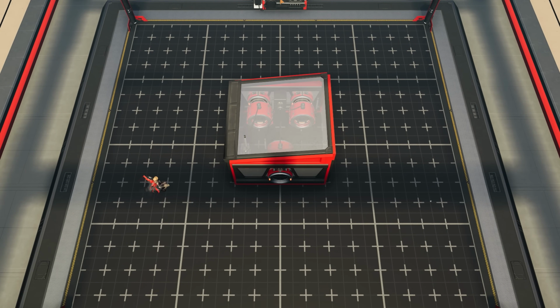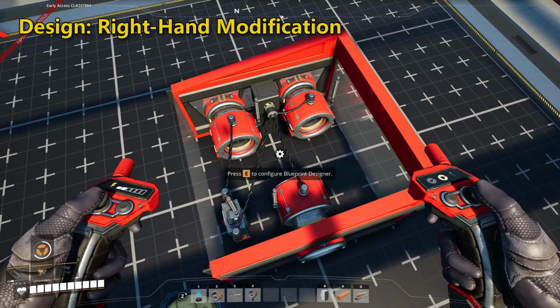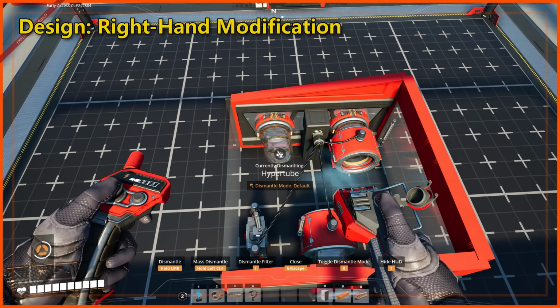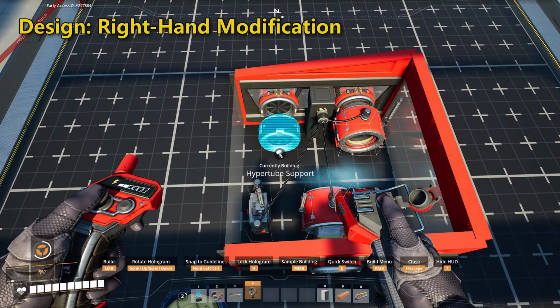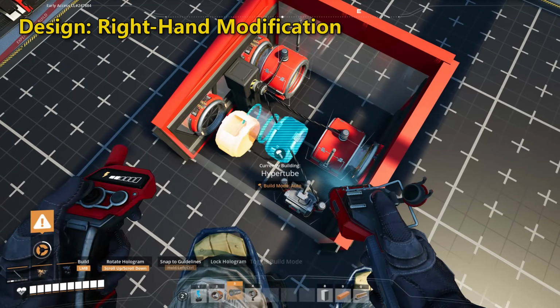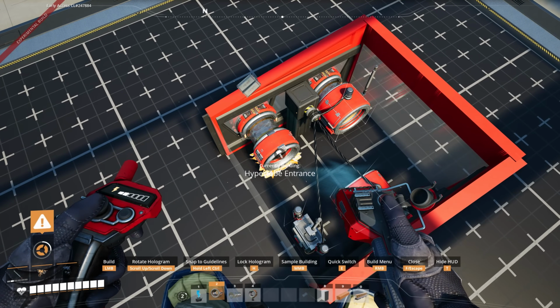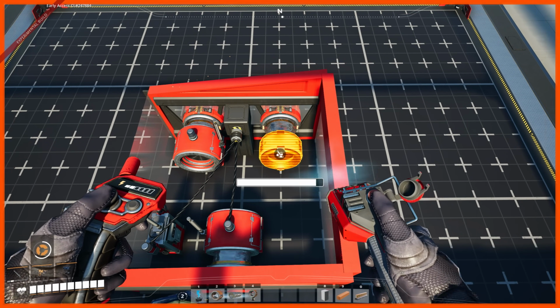This junction blueprint is for a left-hand exit. Let's modify it now to provide a right-hand one as well. First, we remove the priority entrance. This will be our new default entrance. Next, we delete the default entrance from the left-hand one.